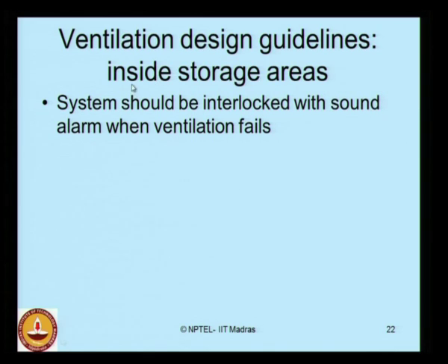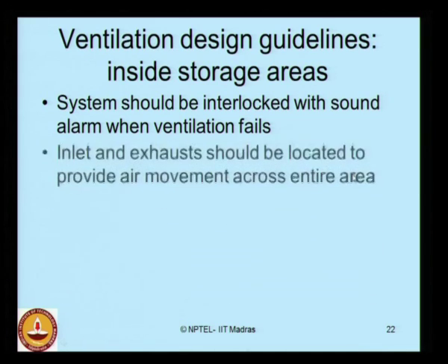In case of inside storage areas, the system should be interlocked with a sound alarm when ventilation fails. This is one of the essential design requirements for an inside storage area. Your system should have a proper network of sensors which are interlocked and raise a sound alarm when the ventilation system actually fails in your storage area.